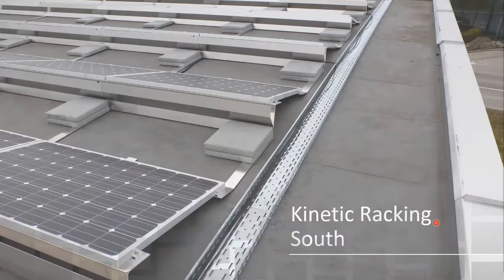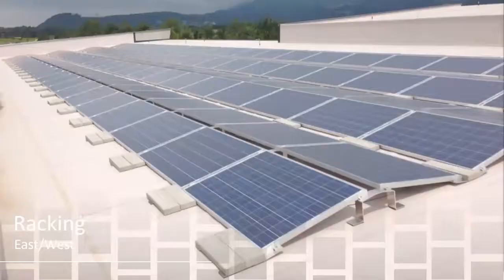So this is a south-facing. One thing I want you to keep in mind if you look at this slide is the spacing between rows. So due to shading, I want to keep spacing. So this eliminates some of the density I could have. Also, I have this wind catch in behind, right? Because if I have hard winds, I need some sort of wind diffuser to stop those panels from lifting, especially here in Atlantic Canada. So an alternate to the flat roof south facing is an east-west racking solution.